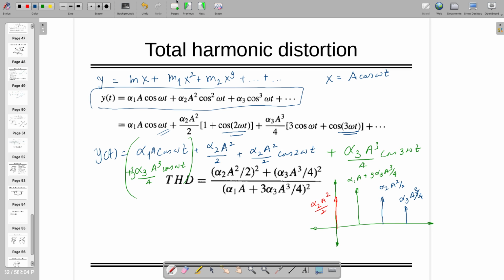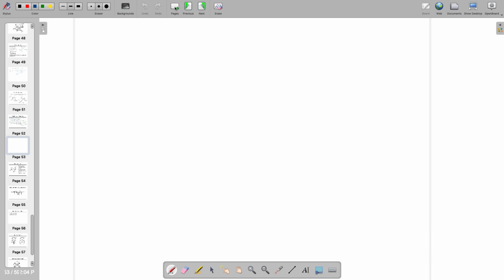So the most important part is how many harmonics need to be taken into account. How many harmonics do I need to take? Up to 8th. Why 8? Because after the 8th harmonic, the power contribution will be negligible. But why do you think only 8? Still, 8 is some magic number.